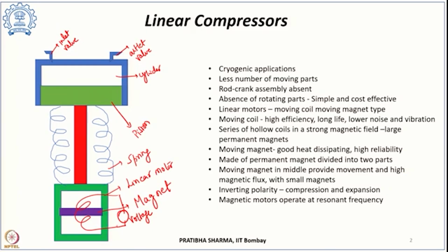So, in these types of linear compressors there is a linear motor, and that is responsible for providing movement to the piston, and this is connected to the piston by means of a resonating spring system. So, the piston movement is provided by this linear motor through a resonating spring system.